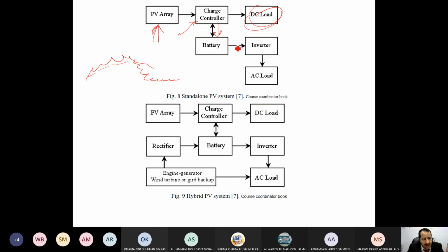And definitely if we have AC, we can connect an inverter. The next topic to be discussed, inshallah, after, in week 8, sorry. And then we provide the AC. Sometimes the battery is not only charged by the DC-DC converter, the buck boost, but also from a rectifier. We can charge it, helping in charging. They can share the charge. As an example, the rectifier could work at night to charge. Okay, at night, because there is no solar radiation, the PV will not provide voltage, power, current, and so to charge the battery, the rectifier will work.